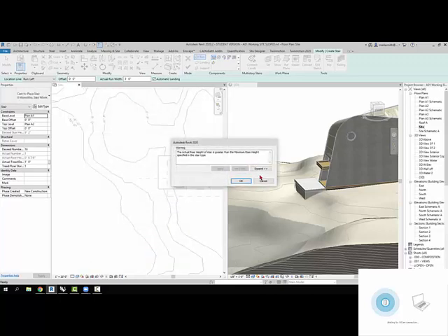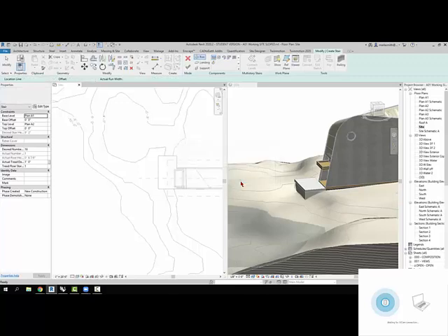I'll click OK, and it's going to yell at us a little bit, and that's fine. Just click OK, and I'm going to set my run to the right. And then I want to think a little bit about where I want the stair to go, because the base level is plan A1, and the base offset, so the bottom of the stair is at -7 feet, let's say, because the water's at sort of -8 feet. And then the top level is also plan A1, but that offset is going to be -6 inches.